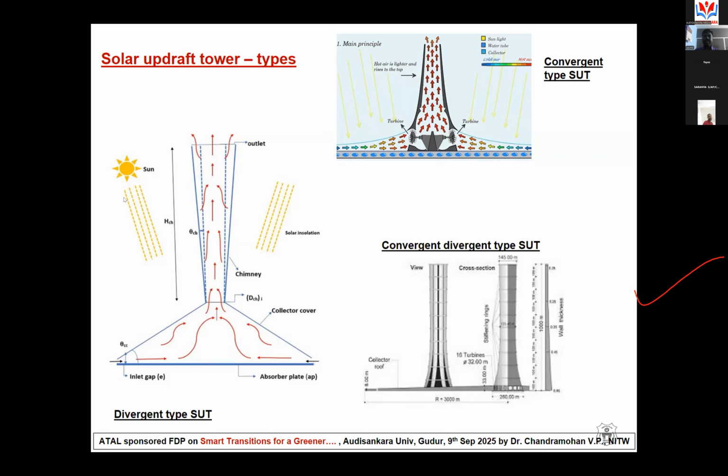The concept is almost the same as the concept of a nozzle or diffuser. The purpose of the nozzle is to increase the airflow velocity. If the airflow velocity is higher, then the air has more kinetic energy. Then the turbine blades can extract more kinetic energy, and therefore the turbine can produce more speed. Therefore, we can extract more electrical energy. That is the concept we are using here.